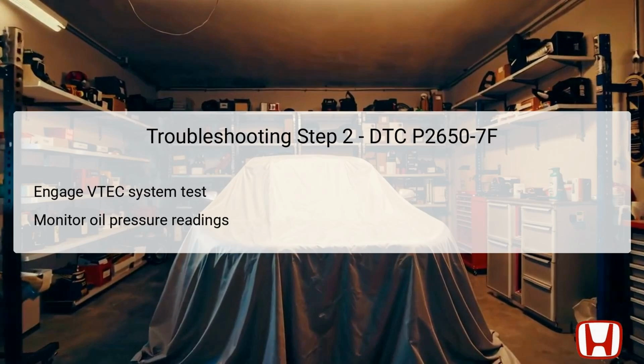Once the engine oil level and rocker arm oil pressure sensor inspection are complete, the second troubleshooting step is to engage the VTEC system test using the Honda Diagnostic System, HDS.